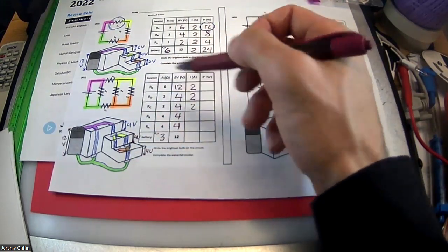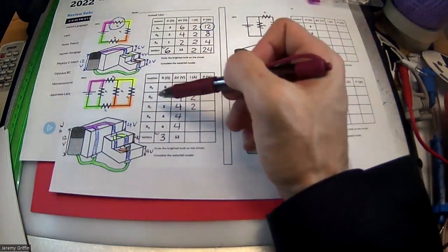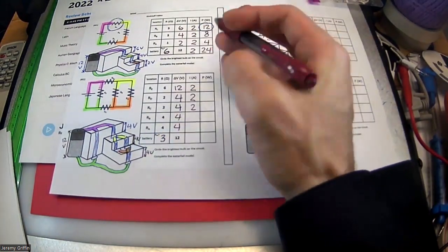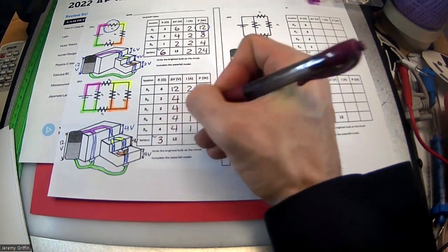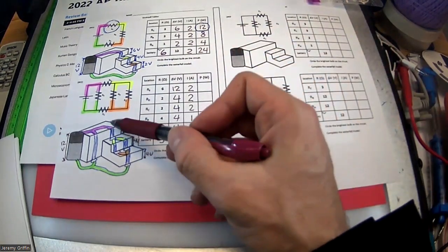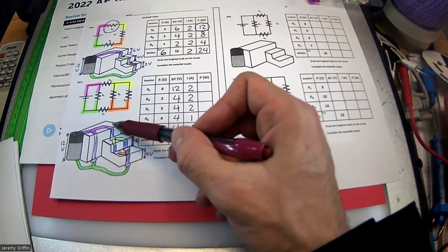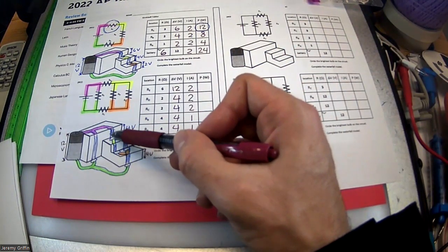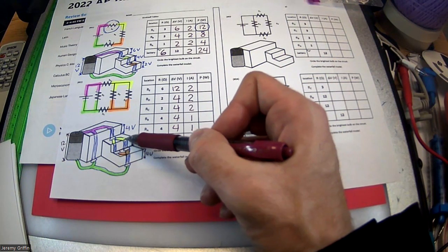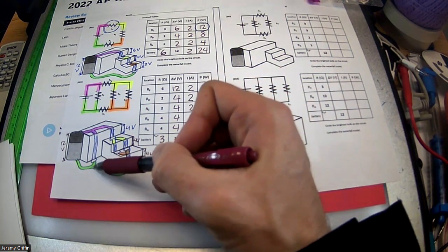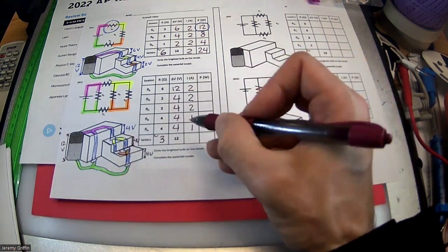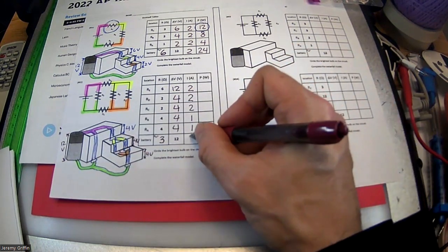Okay, but then here's the middle part of the story. Resistor A and B are in parallel with each other. What happens there? Well, 4 over 4 is 1 amp. And same story here, 4 over 4 is 1 amp. You guys see it splits? So say 2 amps came down here and split 1 amp and 1 amp, and it came back together. 1 plus 1 made 2 again. Right? And then this 2 and this 2, hopefully they combine to make 4. Let's see if they do. 12 over 3. Yep, that's 4.